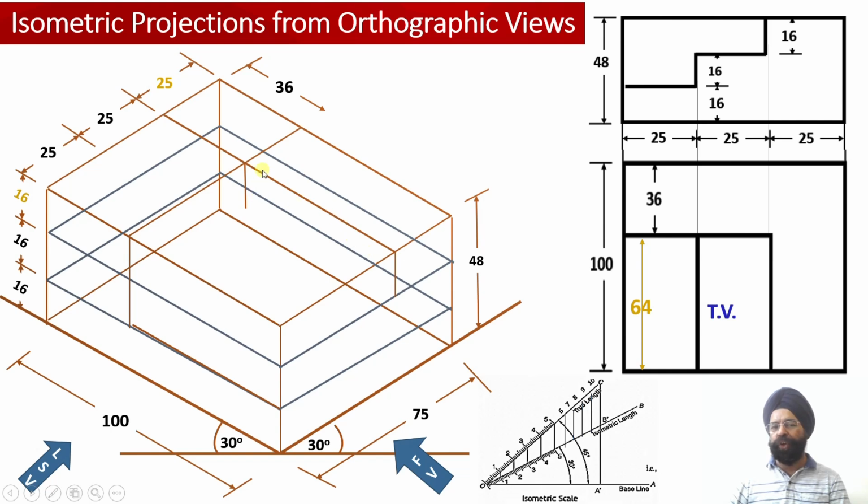Here it is the interior portion. So here I will not be ending on ring number 2, it will be ending on the inner portion of this particular ring surface. Now I will be joining another isometric line parallel to this line over here, so that this flat surface, please check, this corner H which is available as a flat surface over here, can be obtained. So this is the vertical face of step number 3 which has been obtained, and this lies on the top face of ring number 2 over here.